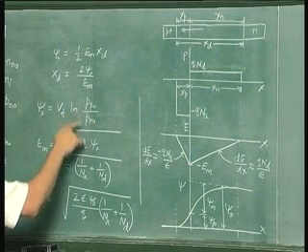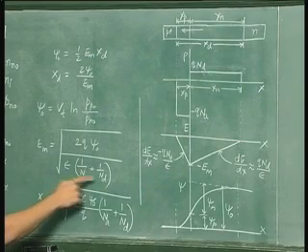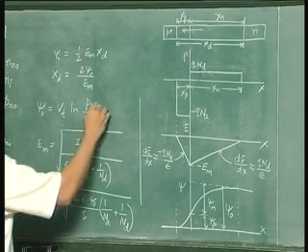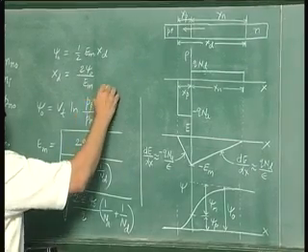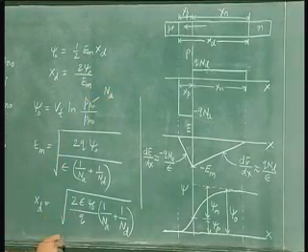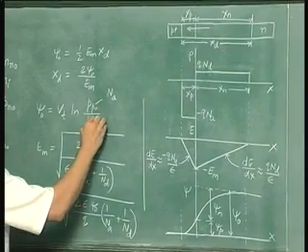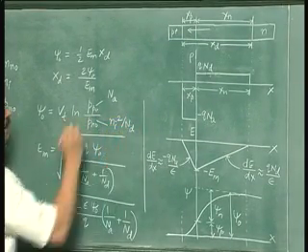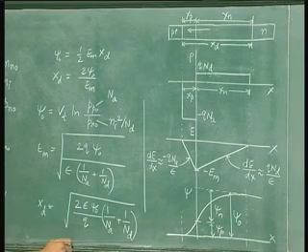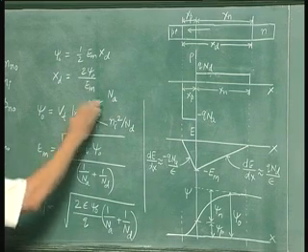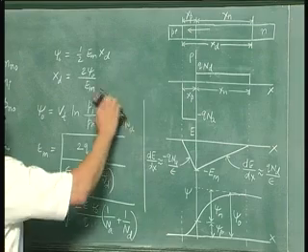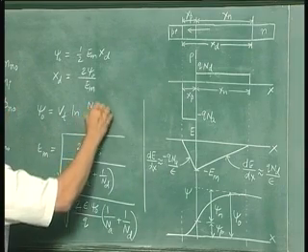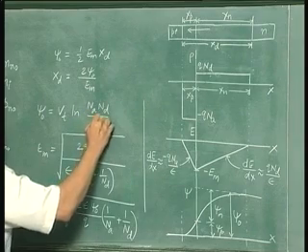Now let us simplify this and get it in terms of doping, because everything we want in terms of doping level in the junction. So pp0 is approximately equal to Na, assuming complete ionization and neglecting thermal generation. pn0 is Ni square by Nd, minority carrier concentration on the n side. So therefore if you put this, you will get the result as Na Nd upon Ni square.